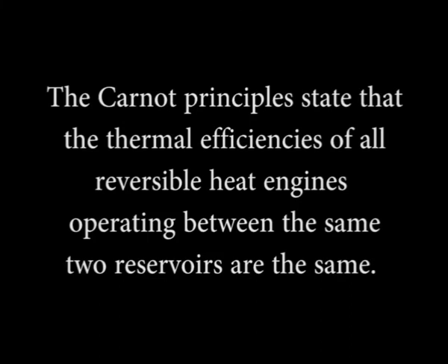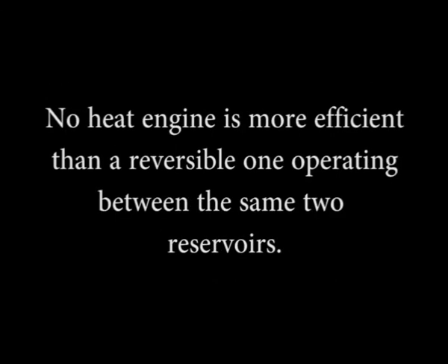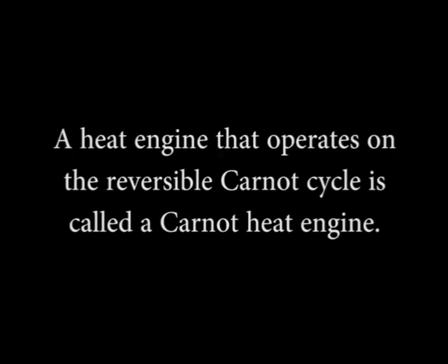So friends, here we come to the end of our discussion and therefore we sum up. The Carnot principle states that the thermal efficiencies of all reversible heat engines operating between the same two reservoirs are the same. No heat engine is more efficient than a reversible one operating between the same two reservoirs. A heat engine that operates on the reversible Carnot cycle is called a Carnot heat engine.